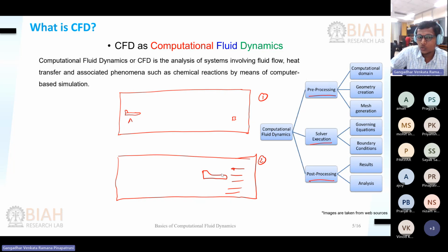So if both are the same, I only look at my second concept. In both ways, you need to set up one frame. Some particular area you need to fix to see your simulation. Because if you want to see the flow over an aeroplane, you cannot take only this small area, or only the aeroplane. You need to take up the space, three-dimensional or two-dimensional. So I'm taking a two-dimensional space like this and placing my aeroplane here. Then only I can see the entire flow field in this space. So two or three dimensional, whatever the dimension is, you should fix your space like this.